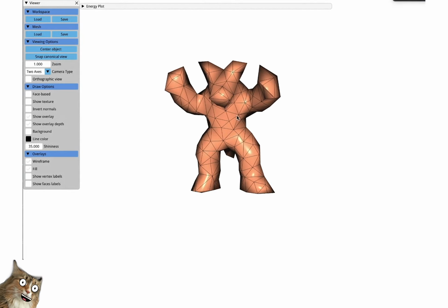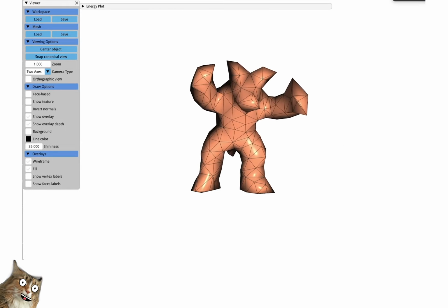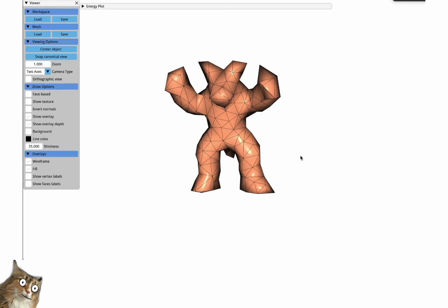What we find is that line search cleans up all the stability issues we were experiencing, which means we've finally seen all the pieces we need to implement a pretty good version of the full Backward-Euler time integration scheme. A reminder that just because we focused on finite element systems in this video, these techniques are readily applicable to the simulation of almost any physical system.